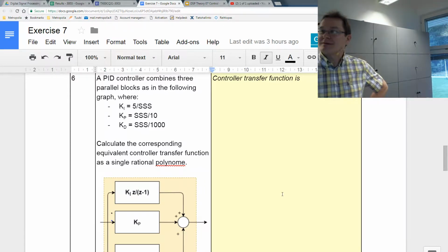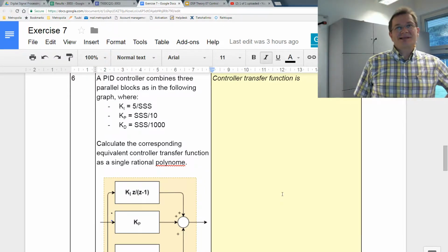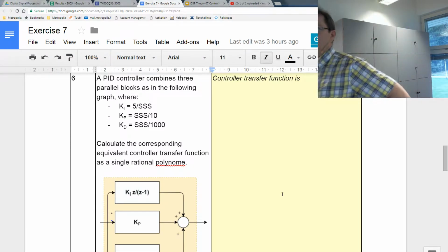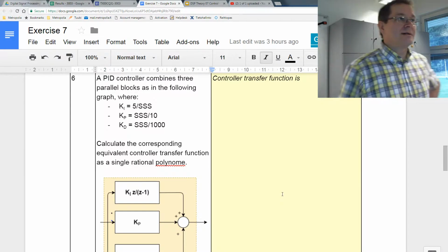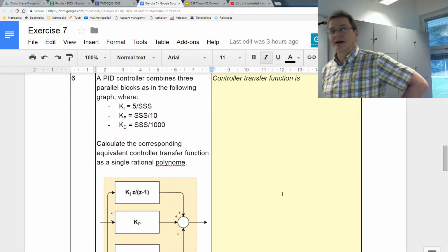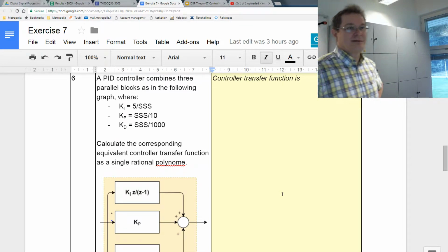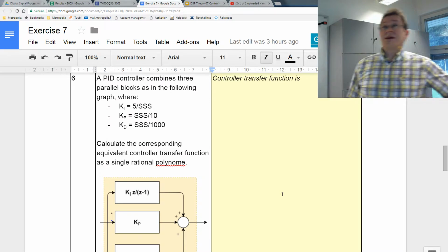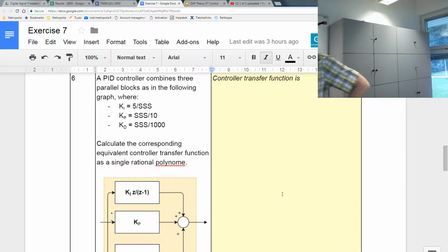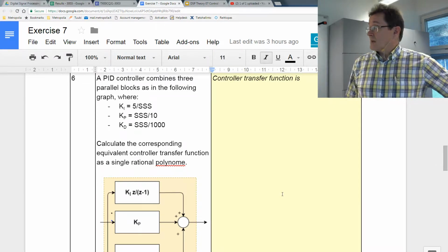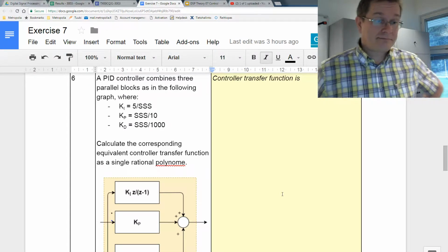With small numbers of SSS you would get quite long settling time and quite short rise time, and with big SSS numbers I think you would get an overdamped system, meaning long settling time, long rise time.